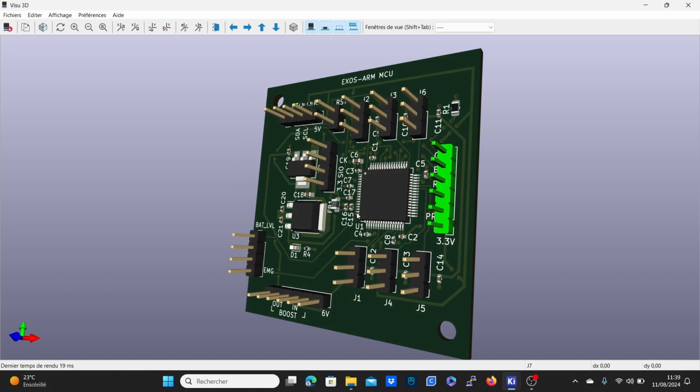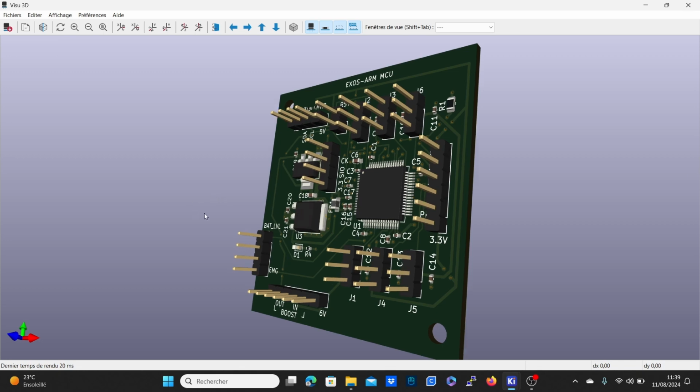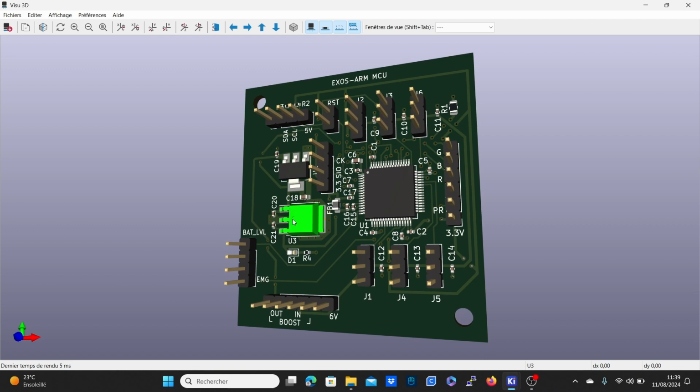The position is not secured like when you're using a JST connector, for example. And the cables, the Dupont wires specifically, can be extremely stiff. And stiffness is a huge problem when it comes to mounting a PCB into some enclosure.